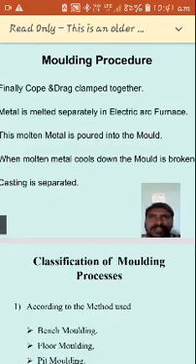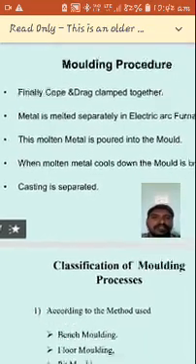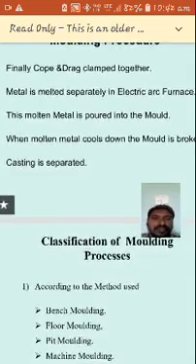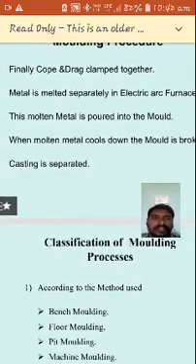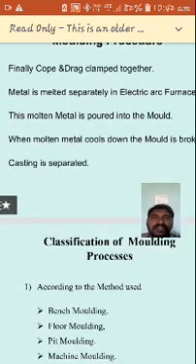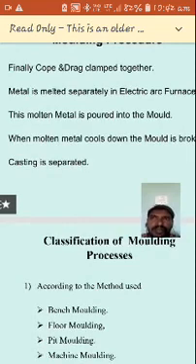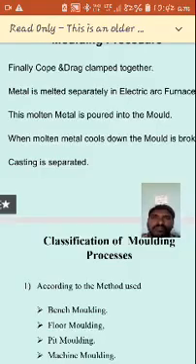If you melt it, that melted metal is called molten metal. That molten metal will be poured into the mold cavity. After removing the pattern from the mold, that becomes the mold cavity. After you remove both patterns, once again the cope will be placed on the drag. Now from the top surface you can pour the molten metal into the mold cavity.